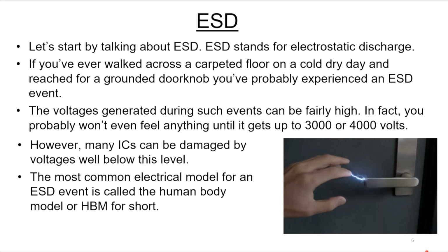So let's start by talking about ESD. ESD stands for electrostatic discharge. And if you've ever walked across a carpeted floor on a cold, dry day and reached for a grounded doorknob, you've probably experienced an ESD event. The voltages generated during such an event can be fairly high. In fact, you probably won't even feel anything until you get up to 3,000 or 4,000 volts. However, many ICs can be damaged by voltages well below this level.